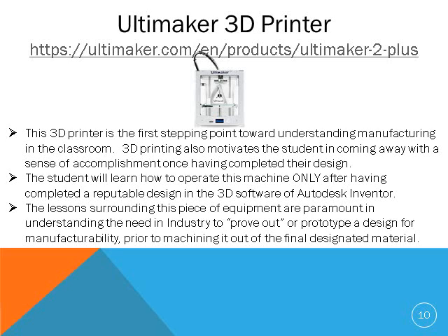The 3D printer is an essential tool that's used in industry as well as the classroom in determining whether or not your design meets the design intent, number one, whatever that criteria may be, but also is able to be made and is ergonomically correct to your specifications. So it gives you an opportunity to 3D print in plastic for the sake of being able to take some measurements and take some inventory on how well that part will prove out in its final material.